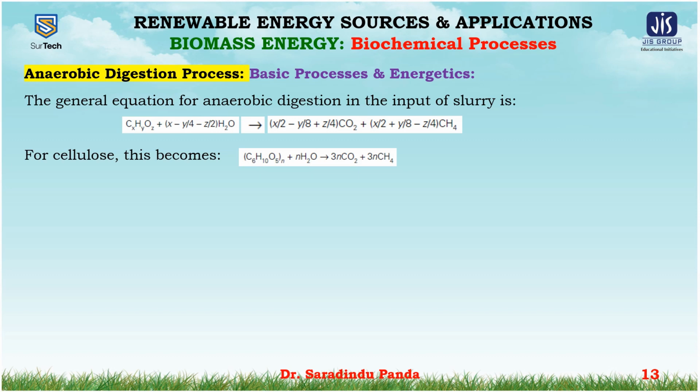In complete anaerobic digestion, only about 10% of the potential heat of the combustion is lost in the digestion process, giving 90% conversion efficiency to the biogas. Moreover, very wet input is processed to give this convenient and controllable gaseous fuel, whereas drying the aqueous slurry would have required much energy, about 40 megajoule per kg of the solid input.